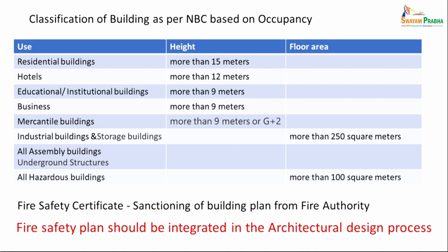As per NBC, we have various categories of buildings. Residential buildings more than 15 meters will need a fire safety certificate. Hotels, as I told, have low calorific value, low fire load, but beyond a certain height they are to be considered under fire safety certification.